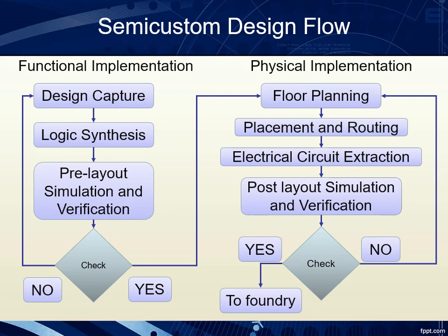Once error-free is achieved, we can now proceed to the physical implementation phase. We need to pass the netlist to the physical layout of the chip. The first stage in the physical layout phase is the floor planning, which means placing every gate in its particular position. The main purpose of the floor planning is to understand the total space that is required by the chip. The exact positions of the gates are less important.